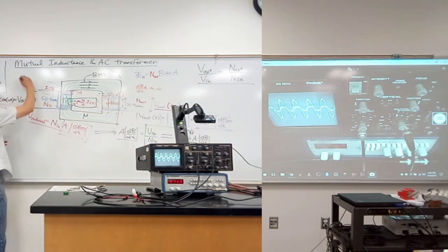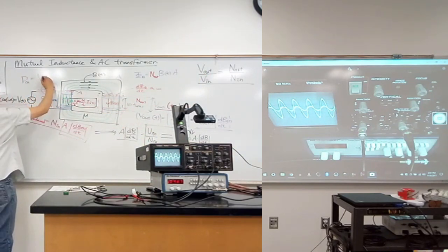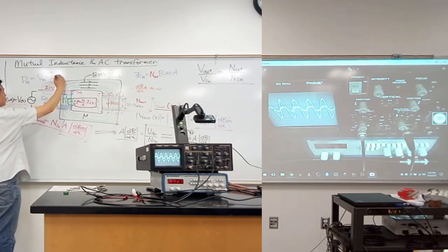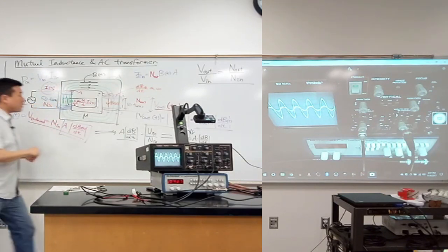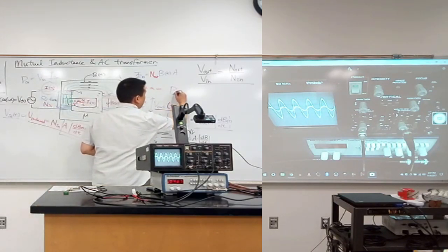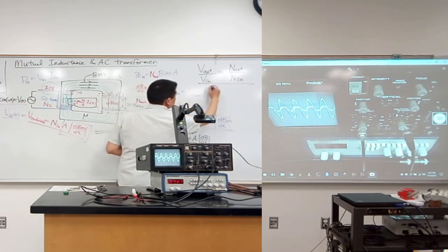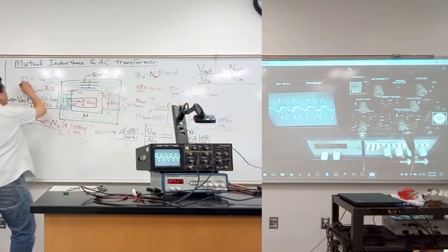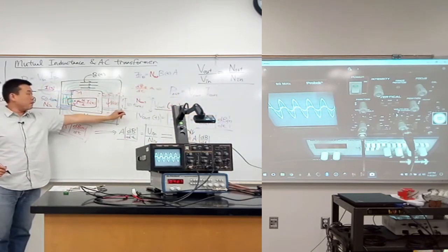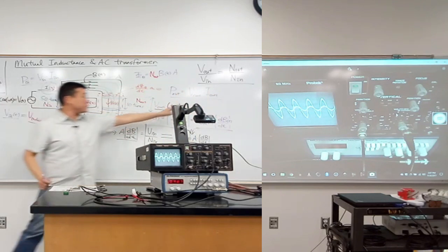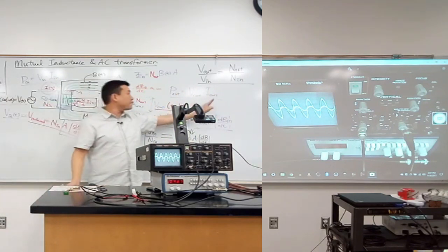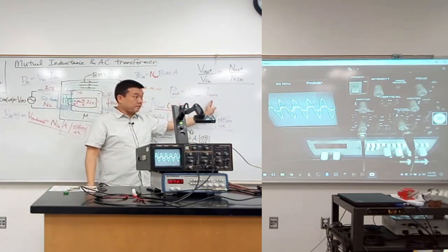So power going in must be equal to the voltage in times current in, and the power going out is going to be equal to voltage out times the current out. So if you build a step-up transformer that increases voltage, your maximum output current is going to be limited.